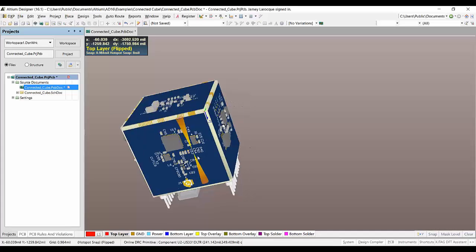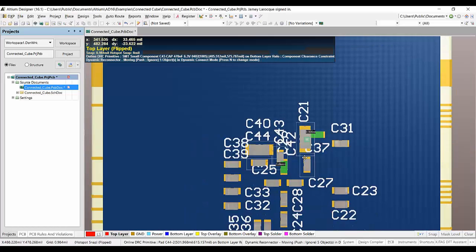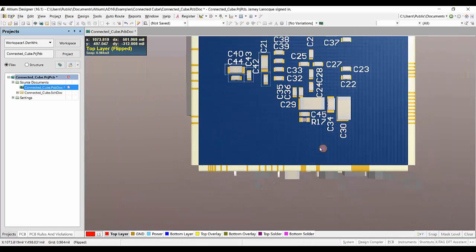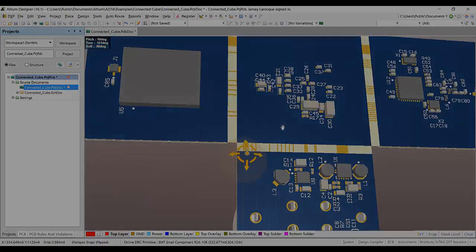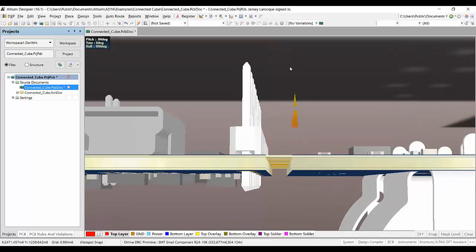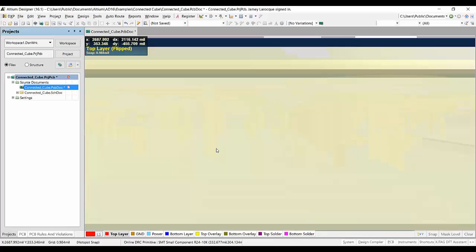More than a simple visualization, Altium Designer's 3D capabilities allow the designer to perform 3D clearance checking. Components can be critically aligned with each other and the enclosure as required. Also, visually locate connectors and other connectors requiring access for servicing. Manufacturing processes and the order of assembly can be better defined knowing all mechanical constraints have been accounted for, as well as 3D animation for rigid flex design.